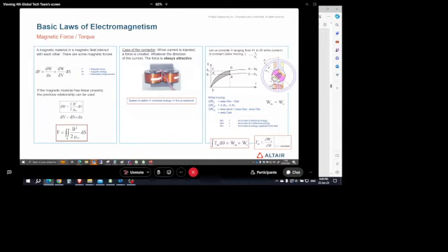Then, if we maximize the magnetic flux, the system will tend to minimize this energy actually. So here, if we take this electromagnet device, if we put this mobile piece on the top, when we supply this coil, we will create a magnetic energy variation, and then the force will tend to move this piece to the bottom, right?